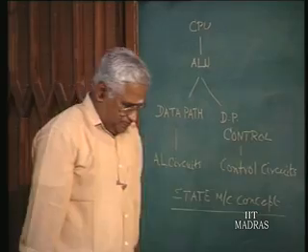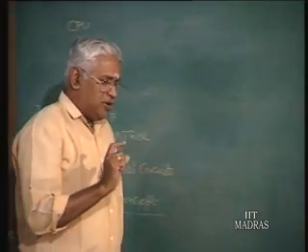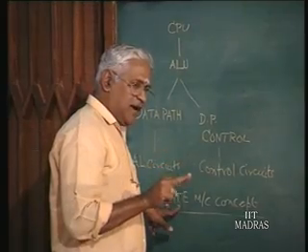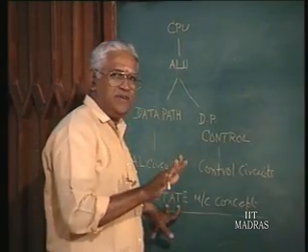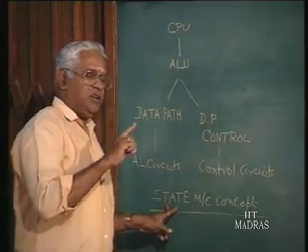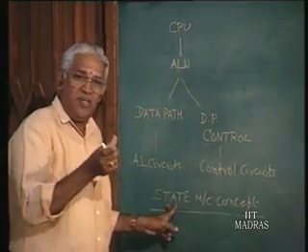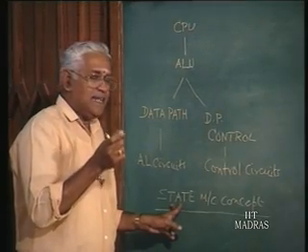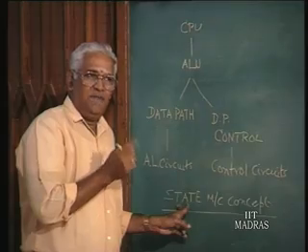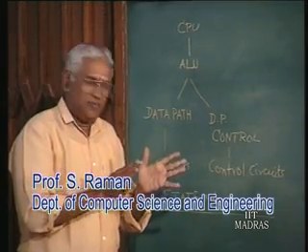Now, what is it? In each state, or the clock period, the CPU enters one state and it carries out some basic activity. Recall, right? That is instruction consisting of machine cycles consisting of states, and in each state some basic activity was going on, and that basic activity is on the data. And within the CPU, what do we have? Essentially we have registers, right?